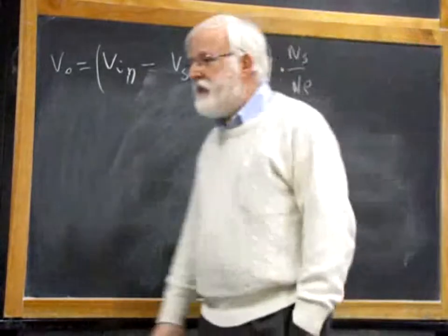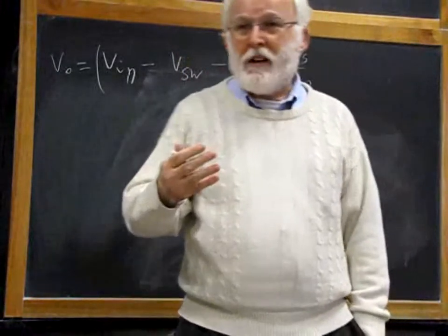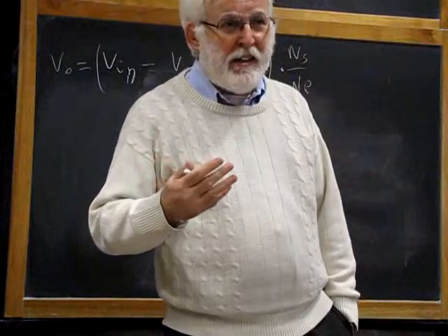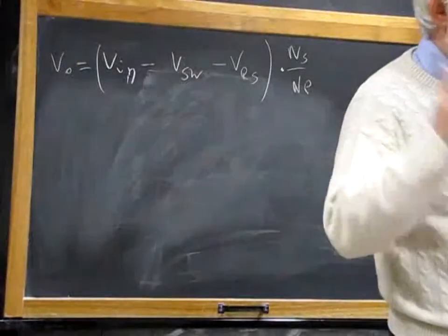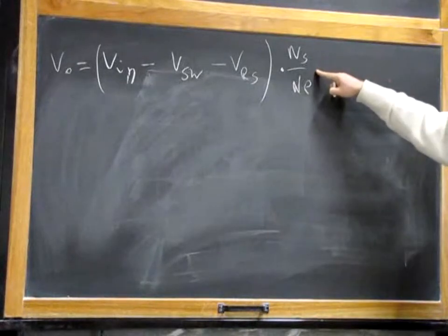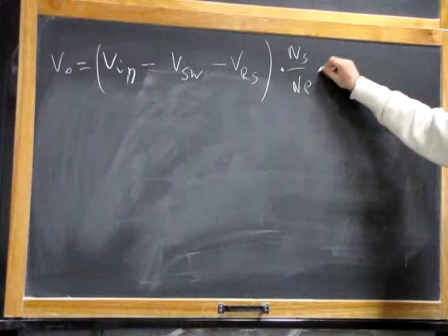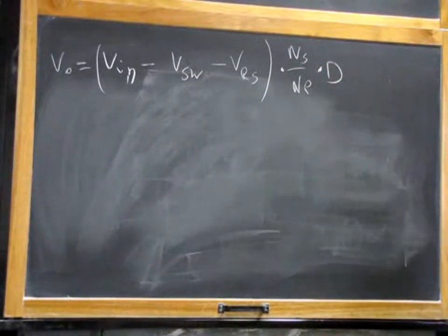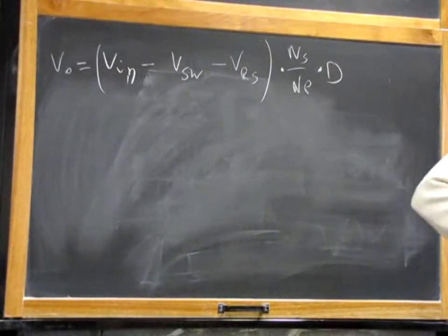This output voltage on the secondary side is applied to a buck converter, a low-pass filter basically. And the low-pass filter extracts the average value of this voltage, and the average value is just the peak voltage, that is this one, multiplied by this side, D. And we still have to consider the voltage drop across diodes. They're both during T on and T off. There is always one diode in series to the output, or two diodes in series to the output. It depends if we use a central tap or a full bridge.